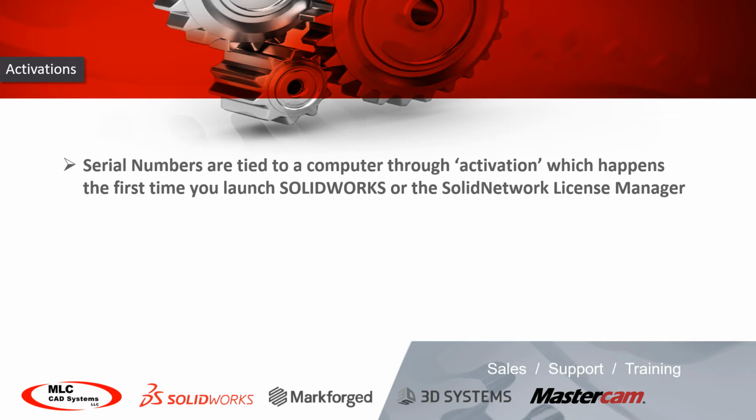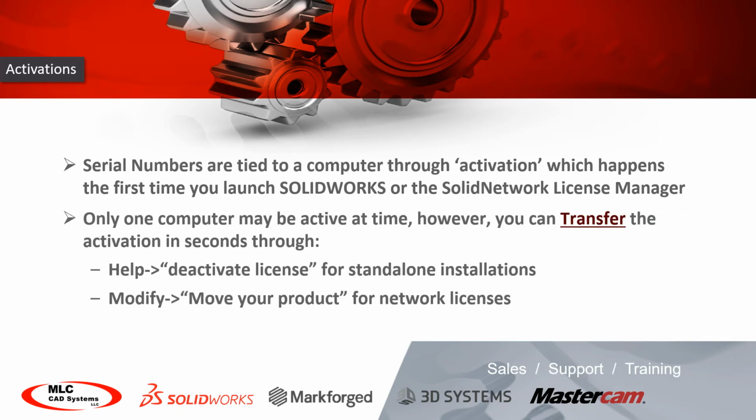Now this does use the internet for that first time that you're activating, but if you have other computers around, don't worry. You don't have to uninstall to use those. You can very quickly transfer that activation from one machine to another. For instance, if I've installed my machine at work and I'd like to use it on my machine at home, I'll simply install on both. When I'm done using the one at work, I'll choose Help, Deactivate License, and then when I get home and launch SolidWorks, it will automatically activate. The same could go for network licenses if you were changing from server to server.